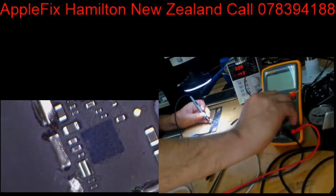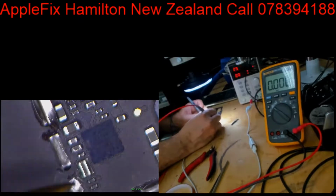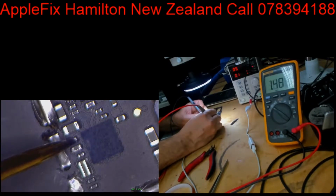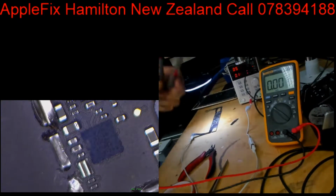Oh sorry, I have to turn it on again. See, nothing here, and then this we have got a 3 volt line. This we were getting, but then dropping, or that was the other line. Anyway, we are not getting it here, which is PP3V3_ACC, one of the power lines.